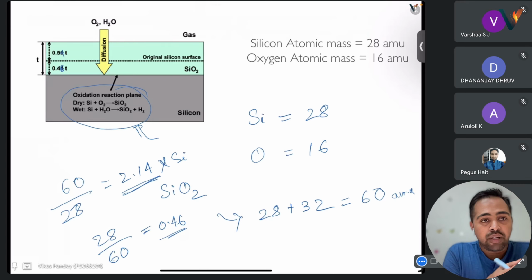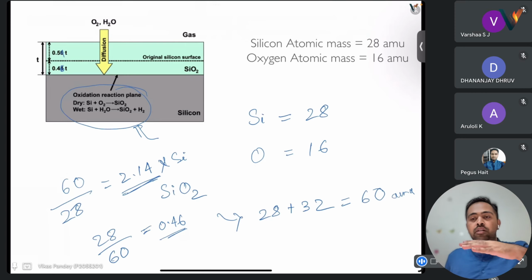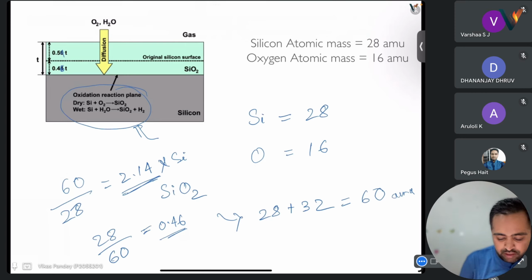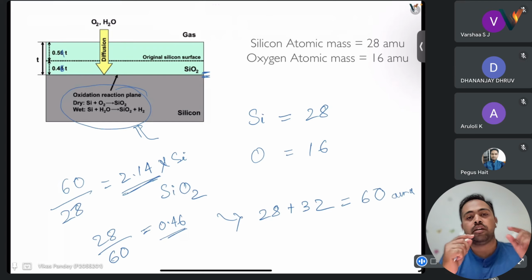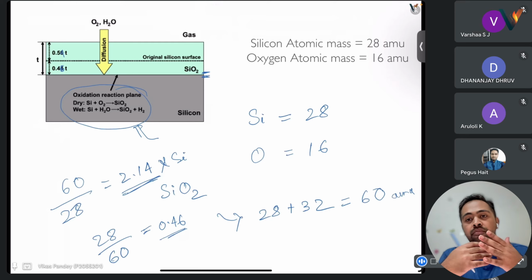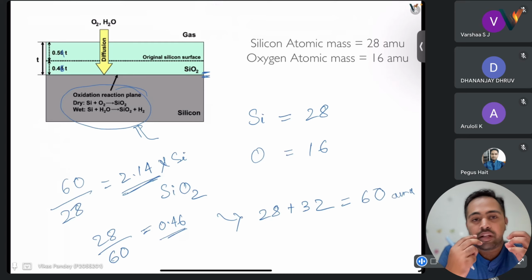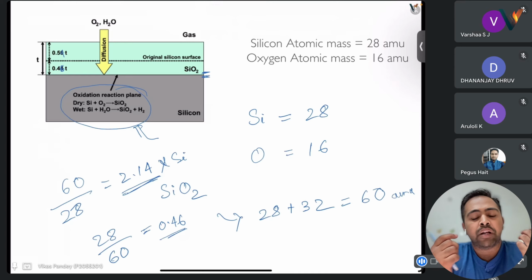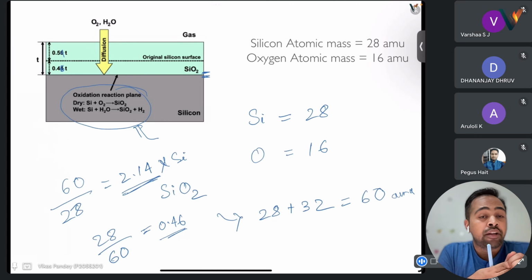Since it takes a lot of time, what is generally done is that since we want the interface where it is connecting the silicon and SiO2, in fact, many times you will hear that it is a God-made interface, very well made. It is one of the best interfaces in the semiconductor industry. With other metals, we are struggling a lot to make it adhere.